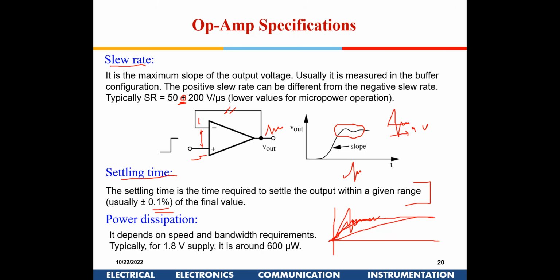In certain cases, if you are sampling this output voltage with, say, a digital A to D converter, the sampling frequency should allow for this settling time. It should sample after this time. That kind of thing can be done.